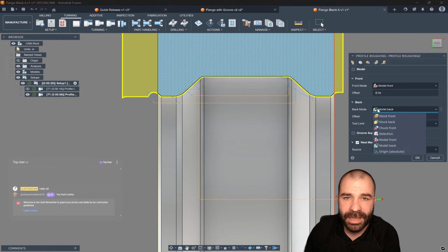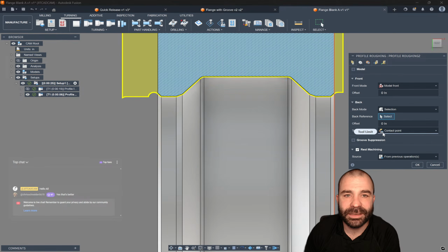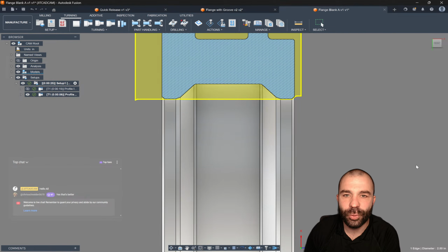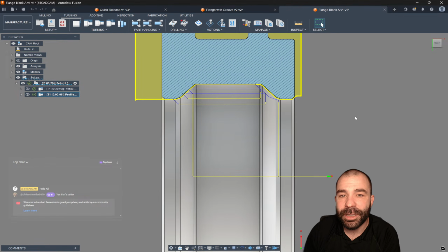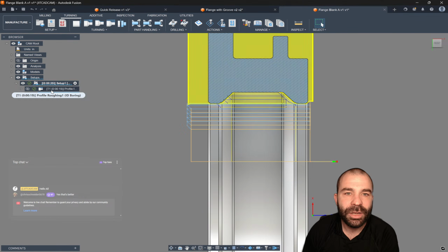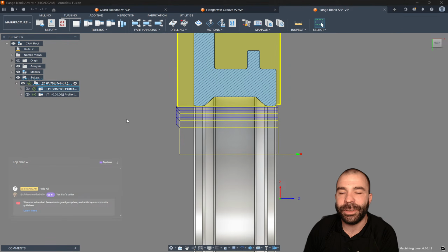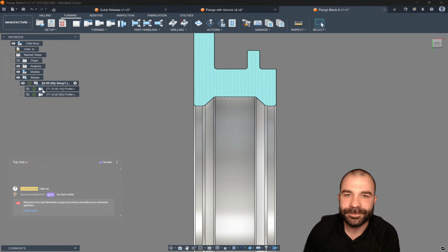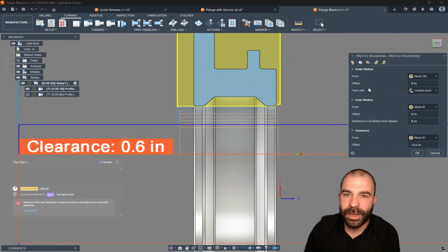No, we are not. So again, I could say selection and narrow down my toolpath to work within a specific Z area. But again, we have that fun of adjusting our radii now, because we may be clearancing way too much, moving a little bit wild and all over the place, and making those adjustments. So again, we jump into radii.